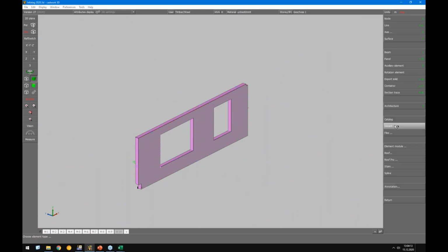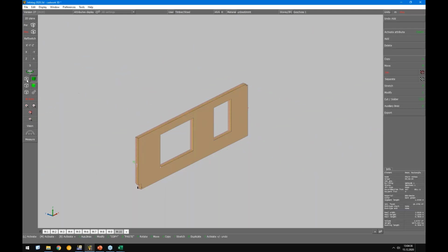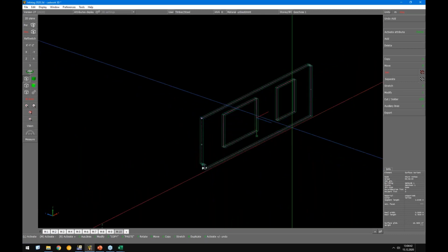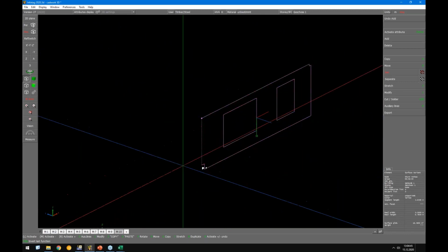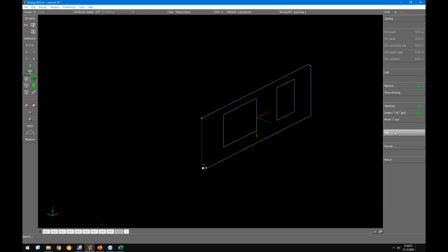Here in this case I can use a variant from CADWork, called, I was not able to rename it, but it's called center surface for CLT. Okay, so I use it and select the element. Then let's go to the wireframe mode. And you can see here the center line or the center surface. This is actually the one and only element I'm interested in. So I have the possibility now to export it as a file. In this case, I use the ACIS export format.